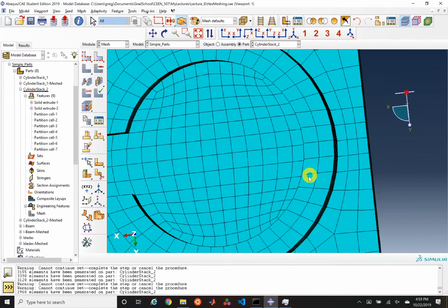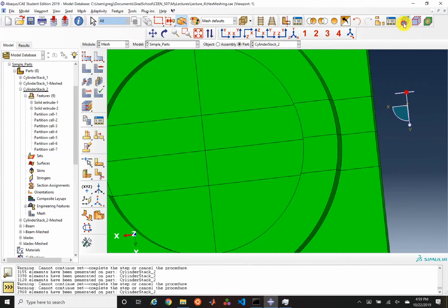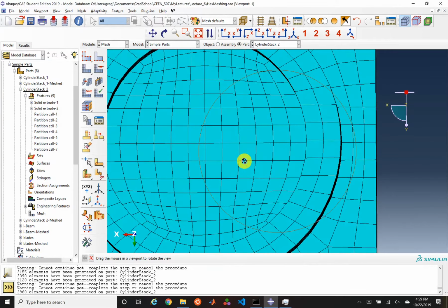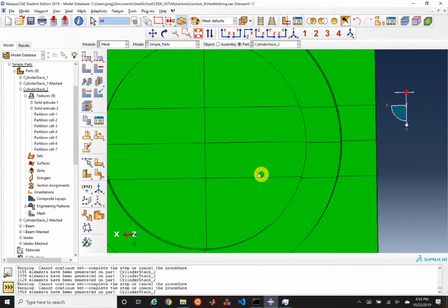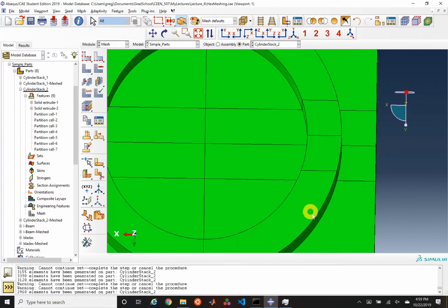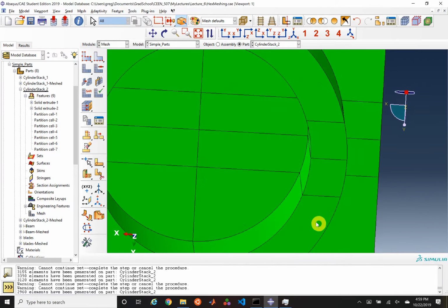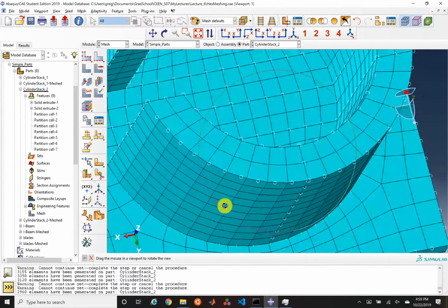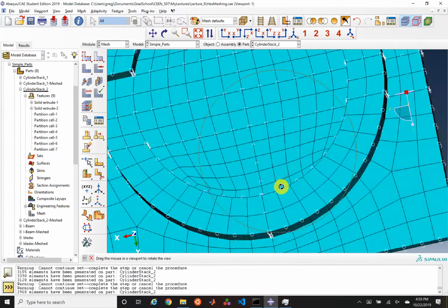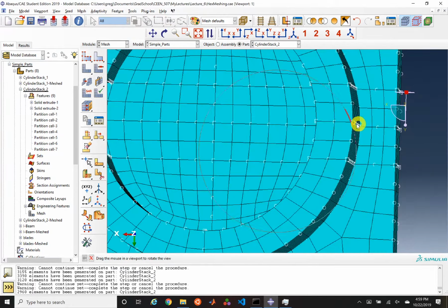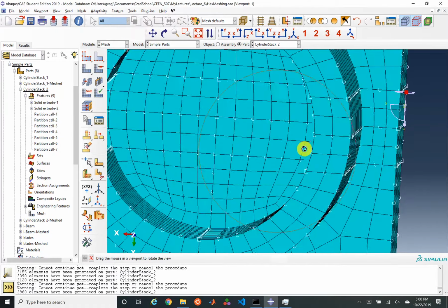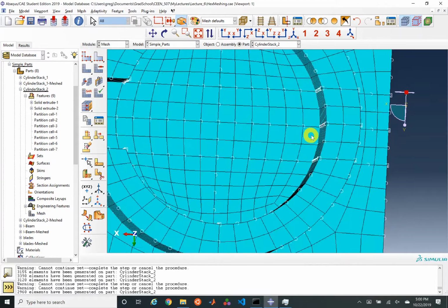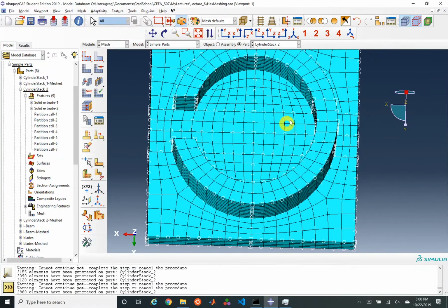What it has done is you can see that if we flip back and forth, there are these element edges here where we've essentially said I need an element that, as opposed to pointing like a ray into the element, like you might see on some of these elements here where they are pointing inwards, is now forced to be skewed a little bit. I mean, they're still good elements, they're still fine, but this is a case where maybe it's one step too far, maybe one bridge too far.